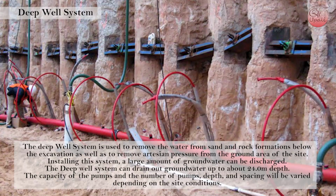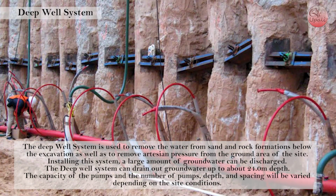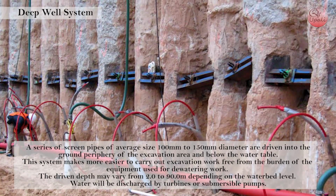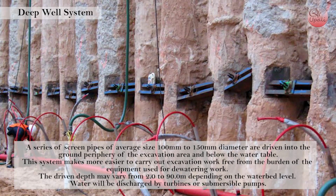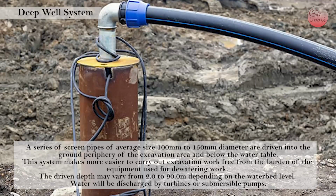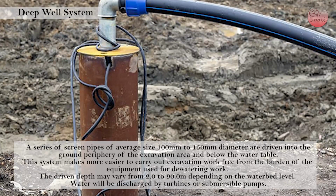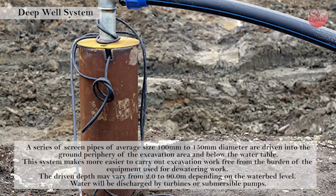The capacity of the pumps and the number of pumps, depth and spacing will be varied depending on the site conditions. A series of screen pipes of average size 100 mm to 150 mm diameter are driven into the ground periphery of the excavation area and below the water table. This system makes it easier to carry out excavation work free from the burden of the equipment used for dewatering work. The driven depth may vary from 2 meter to 90 meter depending on the water bed level.